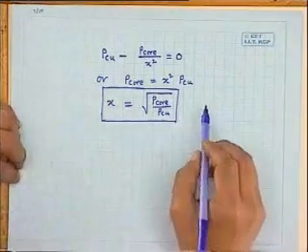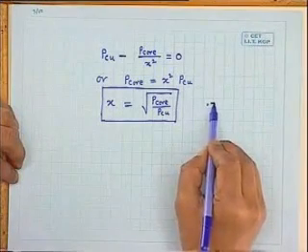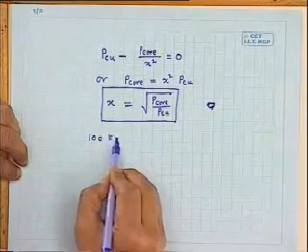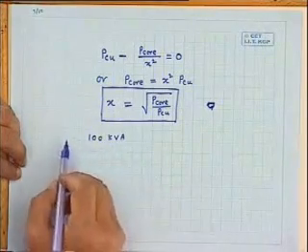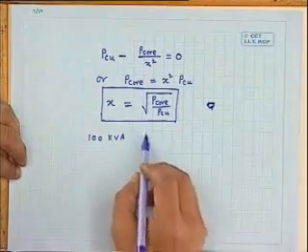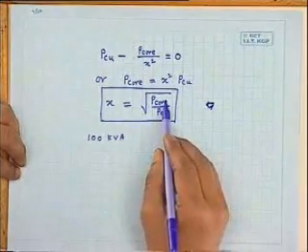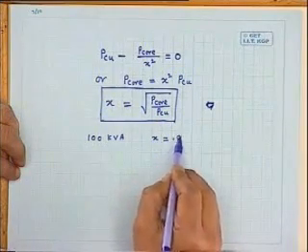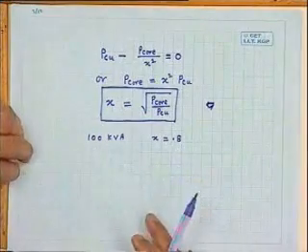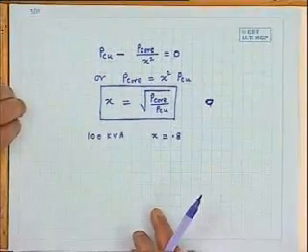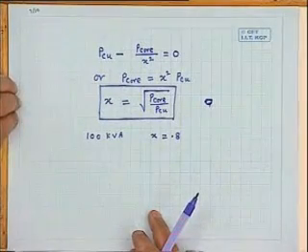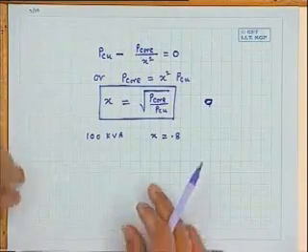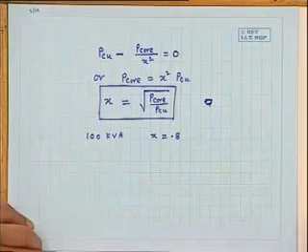Suppose after calculation you find this value becomes 0.7. Just to give you some idea, suppose a transformer rating is 100 kVA. After knowing the value of P core and P copper, you calculate x. Suppose you get the value of x to be 0.8. That means maximum efficiency will be obtained when the transformer is loaded to deliver 80 kVA. Anyway, at this point I will highlight further.